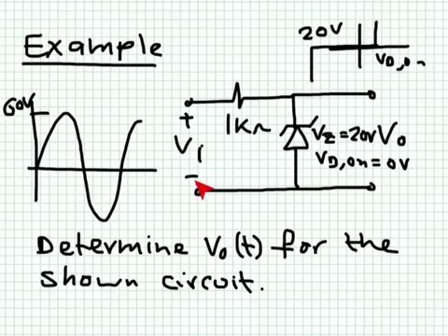the voltage source, or this oscillating voltage source, is trying to push current in this direction, in the counterclockwise direction. It is trying to turn on this diode in the forward region. So once this terminal becomes more positive than this one, this diode will turn on. And when it turns on, the output voltage measured between these two terminals will be 0 volts, because as we agreed, the on voltage is equal to 0. So this whole negative region will be removed.